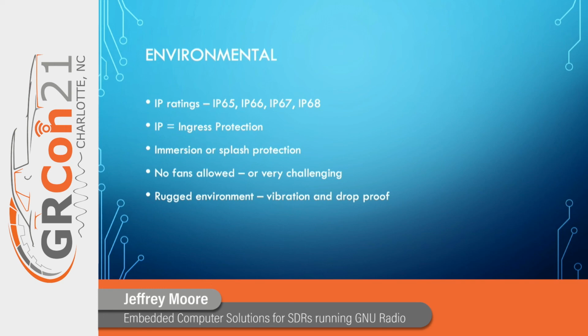Environmental issues, ingress protection standards are always important. Things sometimes have to be immersion or splash proof. We mentioned that earlier with fans. Often a rugged environment's needed because embedded products generally work in an environment that's more rugged than your desktop or laptop. They have to be vibration and even drop proof at times.